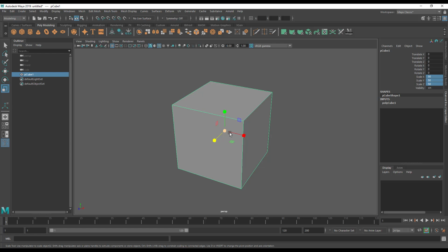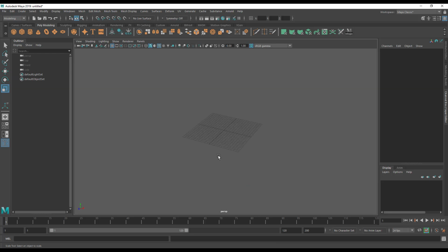It means we can work in millimeters, get the accuracy we need, and as long as we're working in millimeters, we'll be on the right scale. So just something to bear in mind, this wouldn't actually be 50 by 50 centimeters on export, this would be 5. Now this is a little different when it comes to imperial measurements, so inches in this case.